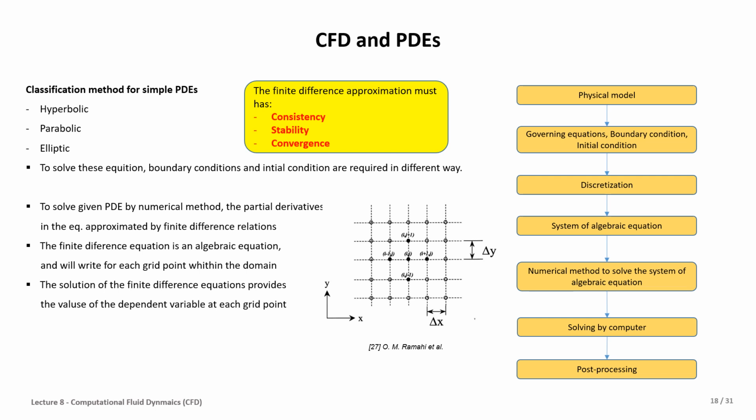Some of them need both of them, some need one of them. However, for example, in the finite difference method, when it's used, it's very important to have the scheme for the solution to have consistency, stability, and convergence, which are three factors. It needs to be checked when we are using the CFD to solve a problem.